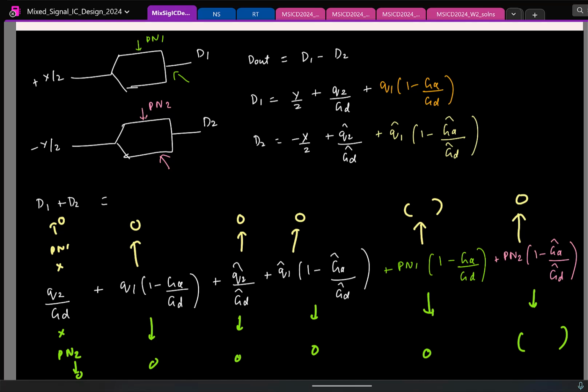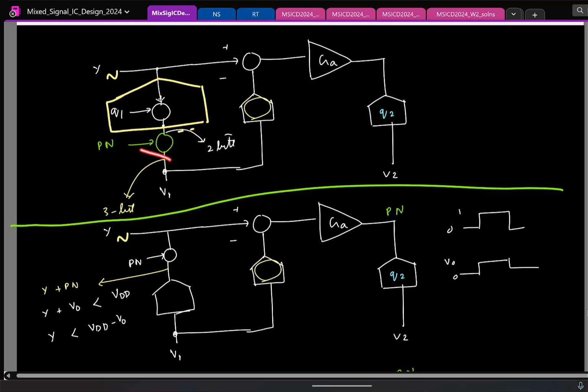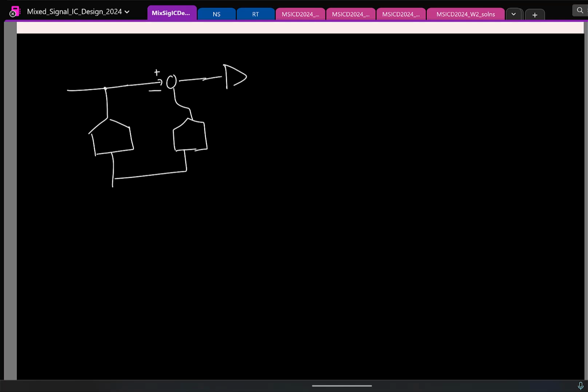Now we have looked at pipeline ADCs and we saw things with flash. As I mentioned in the beginning, whatever ADCs I have drawn here, they can be flash or a SAR. And in practice, the trend is to replace flash with SAR, and that's what is happening. With respect to pipeline ADCs, there is a very good reason to do that, which is the following. If you recollect, in a pipeline ADC, I have one ADC, I need to have a DAC and subtract this, right? And then you amplify it and do this, right?